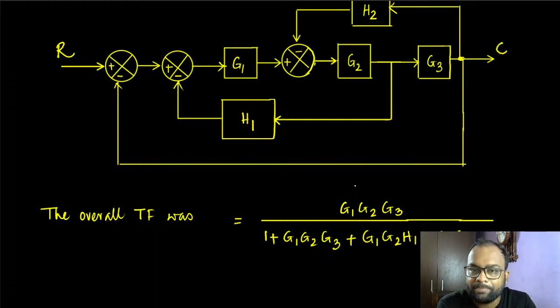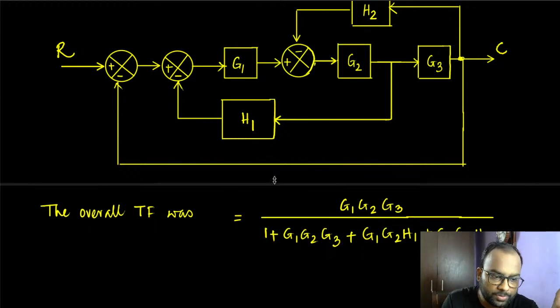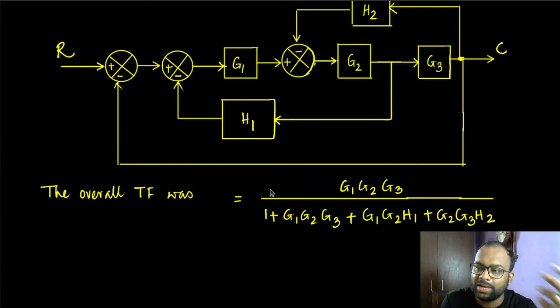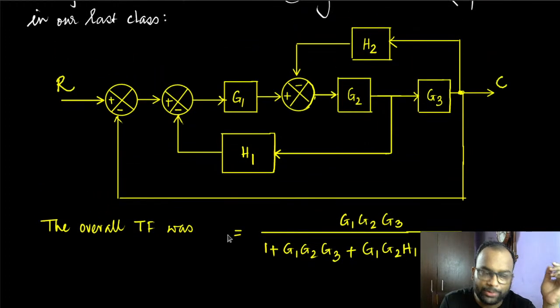Okay, because once again, in this technique, you will learn a certain systematic way of solving it. And whenever you are writing a program to solve the structure of a complicated system, you would want something that is systematic. Because if something is not systematic, you won't be able to write a program for that, right? That's why signal flow graph is so important and so commonly used instead of block diagrams. Okay, and once you learn signal flow graphs quite well, it will pretty much appear to you that learning how to reduce block diagrams was futile. Okay, it would appear to you as such.